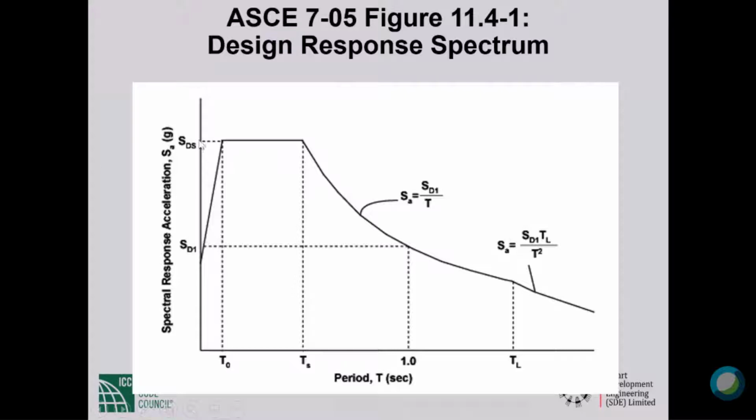The flat top is defined by the ordinate of the spectrum at a period of 0.2 second, and that is S sub ds.